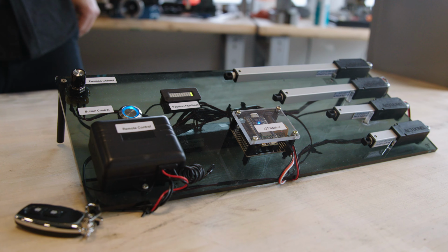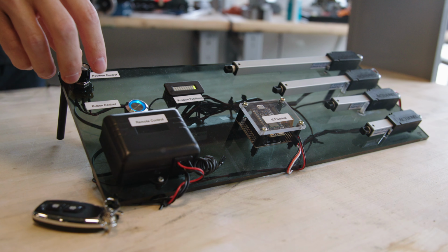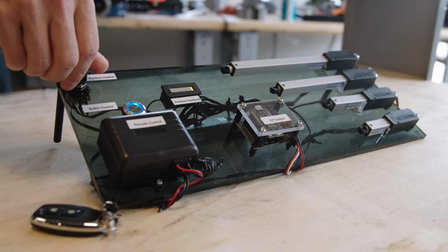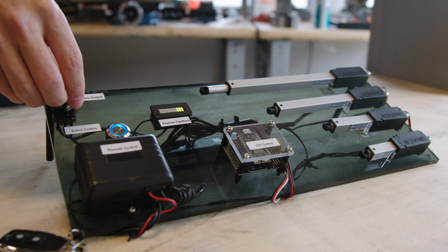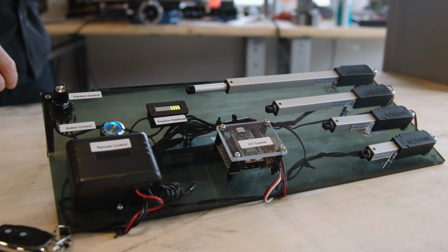Now for performance verification, use a benchtop power supply if you have one, so that you can monitor current draw during the first few cycles. At the full extend and retract positions, you should see the actuator current go to 0. If it doesn't, you may have to increase the timer delay or refer to the actuator datasheet to ensure you have selected the correct gear ratio for your application.